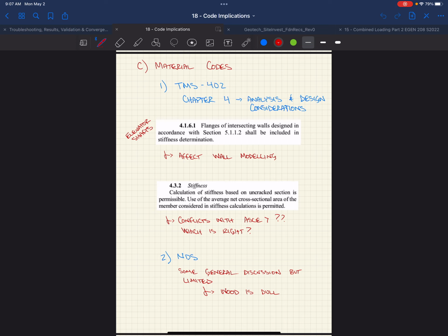So just consider some of those things when you're designing, because when you're designing special brace frames or moment frames, you have a fuse, right? That piece of the puzzle that's going to be getting destroyed in an earthquake, where all the energy is coming out of it. Okay, so it's critical that you design this appropriately.